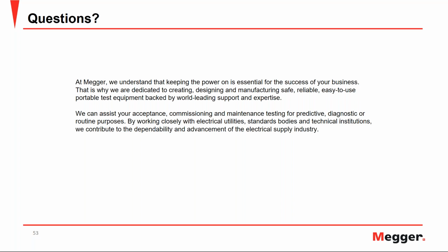However, as we saw during the presentation, the power factor testing has some limitations. When you have a power factor result that is increased, or we detect a trending issue, or the values are increasing in the trend, then the outcome is always investigate.